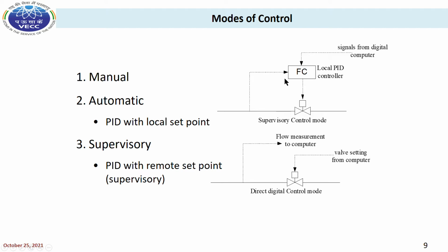So this is a typical feedback control example. Generally a PID controller is used, that is a proportional integral derivative control. In proportional control, the correcting action is proportional to the deviation, and in the derivative it is proportional to the rate of change of deviation. In integral, the rate of change of correcting action is proportional to the deviation. So there are several methods for tuning PID loops.